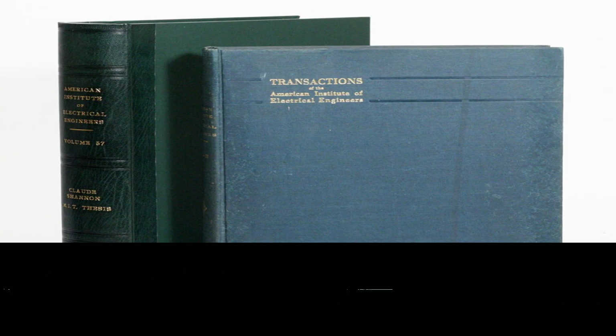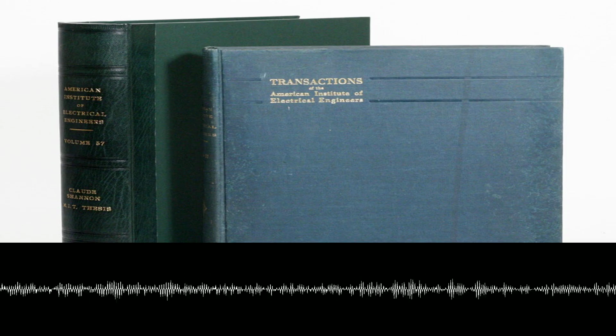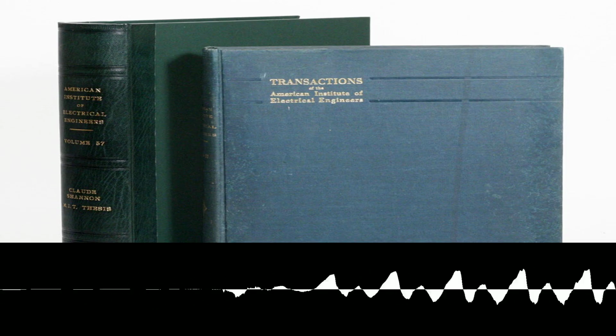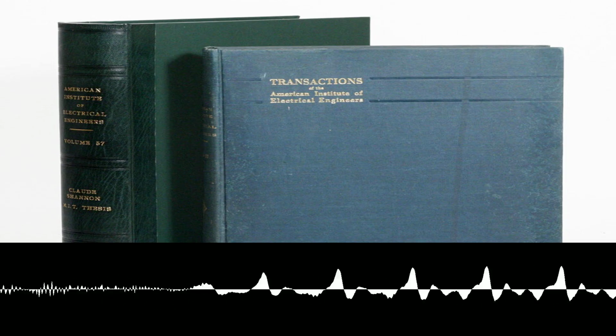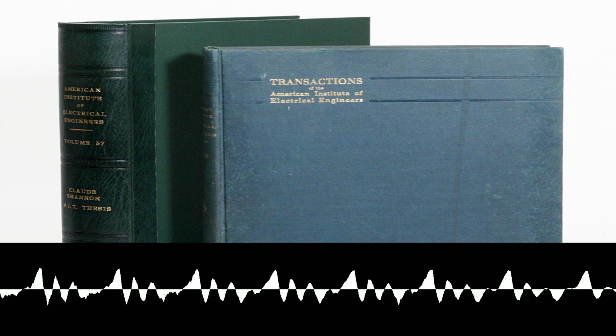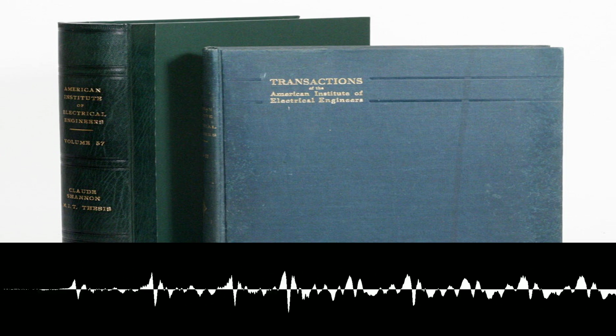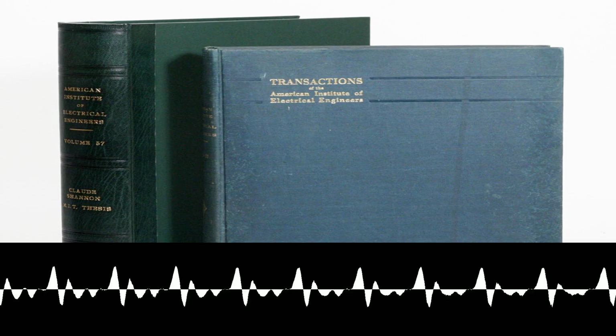Shannon introduces the concept of equivalent circuits, where different circuit configurations can perform the same logical function. The principle of equivalent circuit replacement offers greater flexibility in design, permitting the selection of the optimal circuit based on other considerations, such as component availability or reliability. He presents methods for analyzing and transforming contact networks using his symbolic algebra.